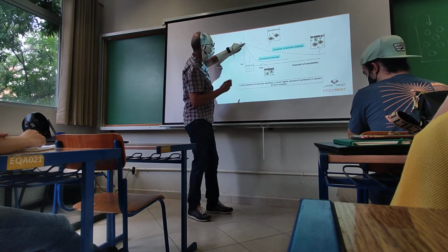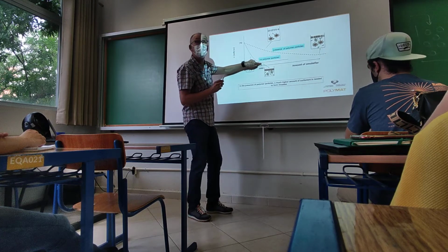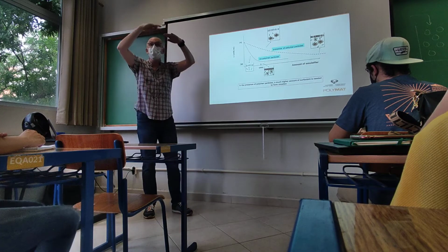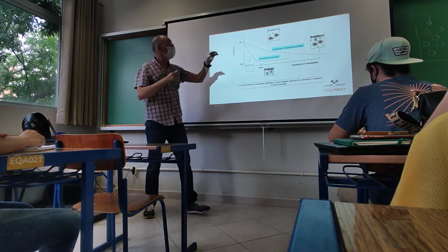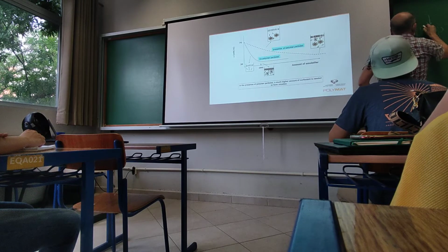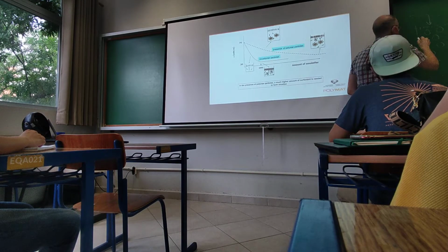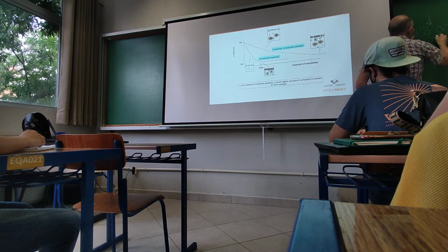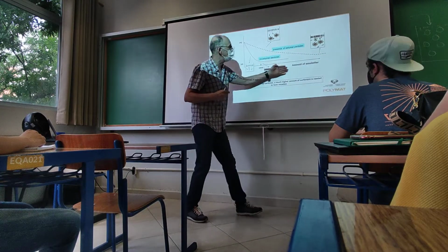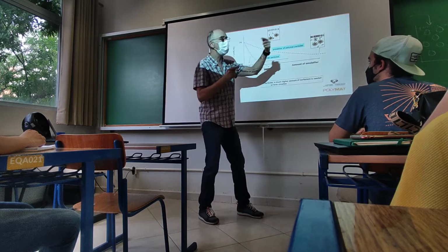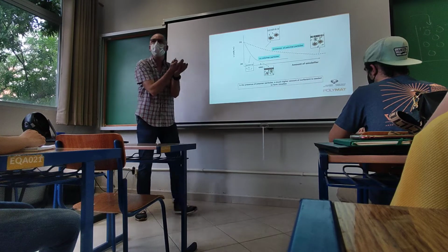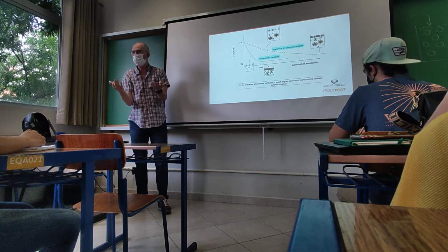In pure water, the surface tension decreases faster because there is no other surface than the air-water interface. But if you have polymer particles, the surfactant, in addition to covering this interface, will go also to all this interface. So you will need much more surfactant to be added to cover all the particles and to reach the point in which you saturate all the surfaces and micelles will appear.